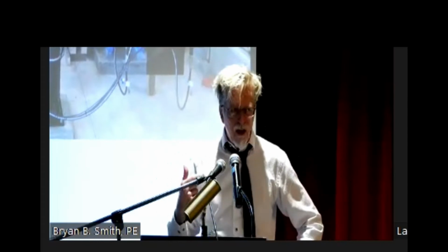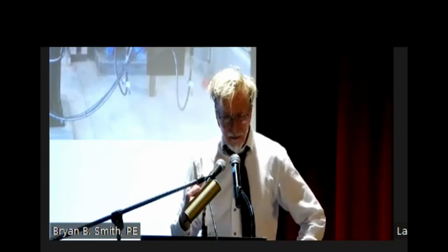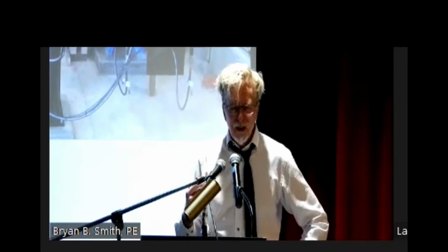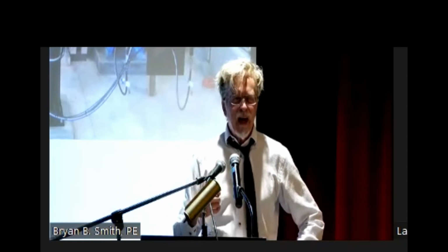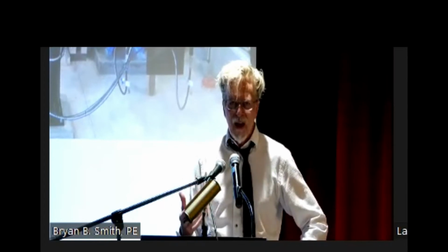When I go to turn off the pump, as we discussed earlier, that change in velocity in the system, if it happens too quickly, I'm going to go negative. So using Joukowski's wave equations or using a surge modeling software, we're going to calculate how slow we want to close the valve.